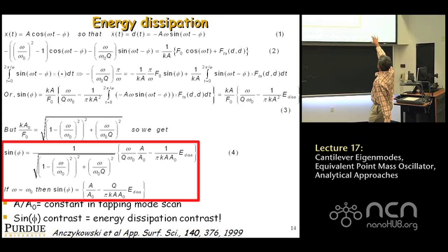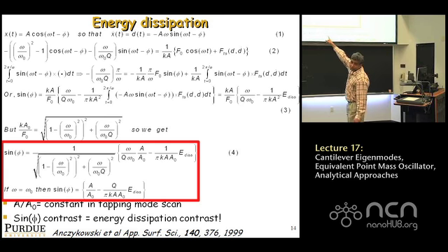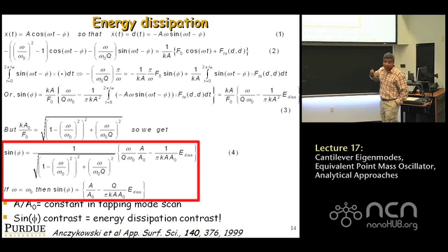So when you multiply through by sine(omega t minus phi), you get the following. You get the negative omega over omega 0 Q times pi over omega equals this quantity on the right-hand side. You can rearrange that a little bit and write the expression for sine of phi as kA over F0, F0 is the magnitude of the forcing, times, in curly brackets, omega over Q omega 0 minus 1 over pi k squared times the integral.